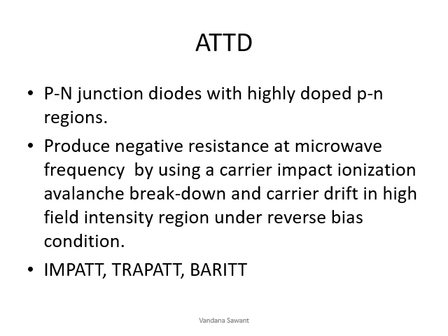Now we will move to another diode, that is the avalanche transit time devices or avalanche transit time diodes. What are avalanche transit time diodes? They operate upon the avalanche breakdown effect, so this is called an avalanche transit time device. Avalanche breakdown is always observed in the reverse bias condition, so these devices are always connected in reverse bias.